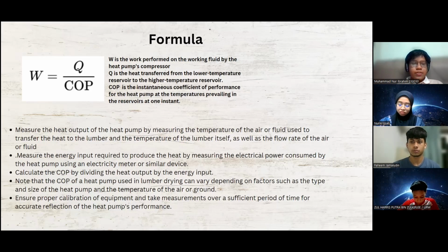Note that the COP of a heat pump used in lumber drying can vary depending on factors such as the type and size of the heat pump and the temperature of the air and ground. Ensure proper calibration of equipment and take measurements over a sufficient period of time for an accurate reflection of the heat pump performance.